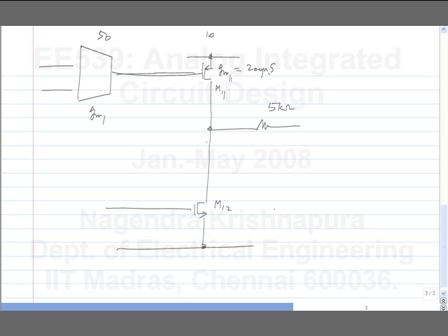How much current would be required here? An estimate of the current. That actual swing will, in fact, make the current more. But just looking at this, you have GM of 200 microsiemens, and let's say you have VD-SAT of 200 millivolts. I don't know, I'm just guessing. So 2 times ID by 200 millivolts is 0.2 millisiemens.